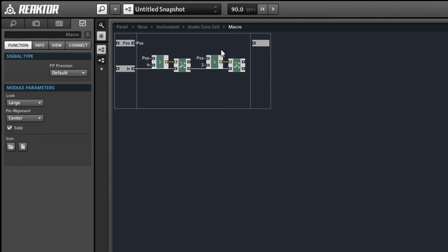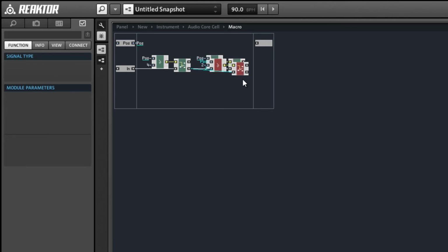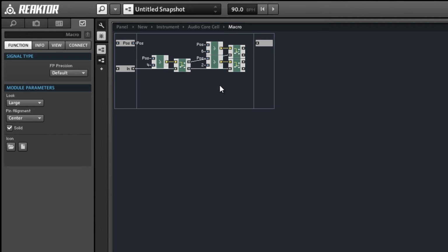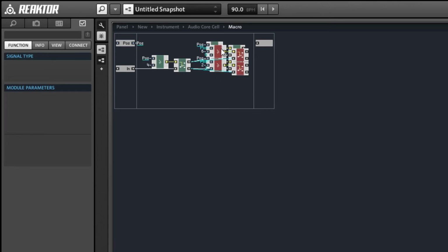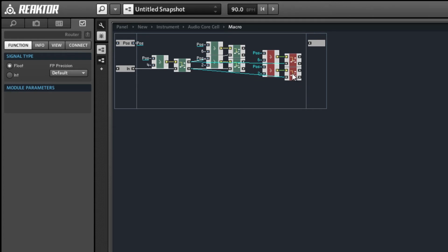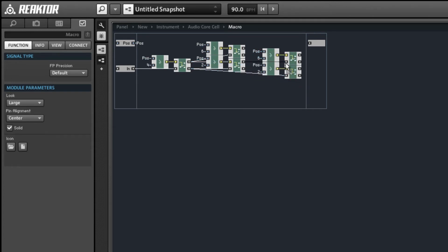So if we get something out the bottom output here, we know that we have a value from 0 to 3. So we can check to see if it's greater than or equal to 2. And if it is, then we know that the position is either 2 or 3. And if it's not, we know that the position is either 0 or 1. So we're constantly just taking the values and splitting them in half. So our upper structure is going to get a position of 6 for this iteration.